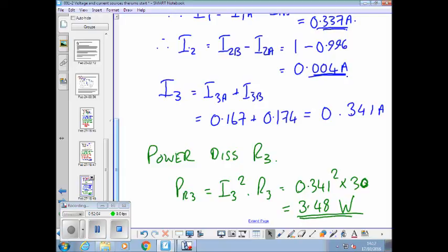Norton's and Thevenin's won't do that. Norton's and Thevenin's will simplify the circuit, and that's useful because you can use the simplified circuit to see what happens when you change the load. Whereas if you tried to do that with this circuit, you'd be doing all those calculations over and over again. As you'll see, Norton's and Thevenin's make that easier.